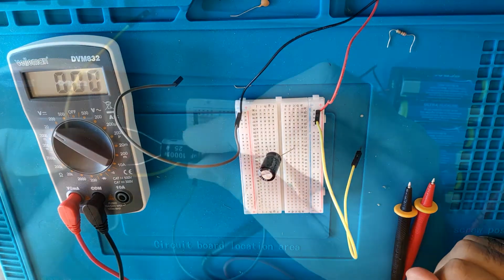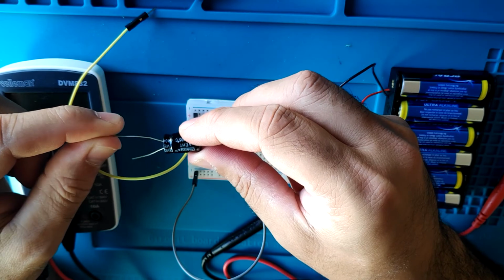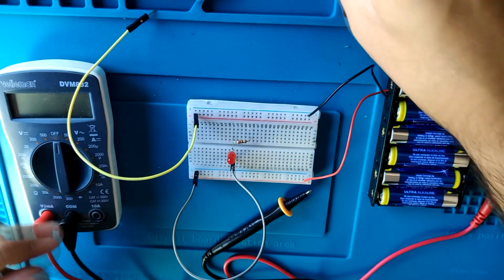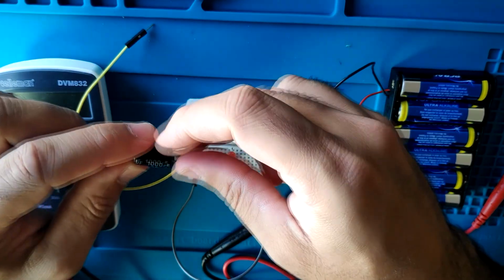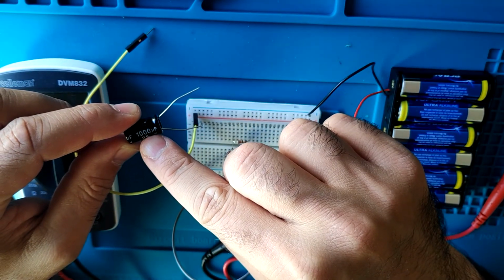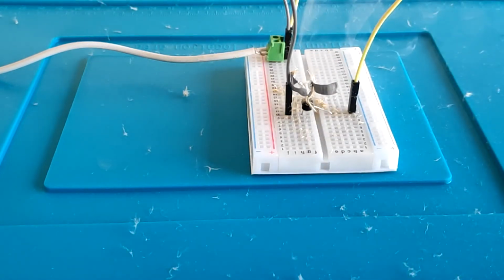On electrolytic components, capacitance value is usually written on the side. Also, the maximum supported voltage. Connecting an electrolytic capacitor wrongly or exceeding its parameters could lead to a very exothermic reaction that could cause injury to anyone nearby. Let me show you. I will connect this component to a higher value power source than supported. Trust me, it was a loud sound. And pieces of the component could be found all around the room.